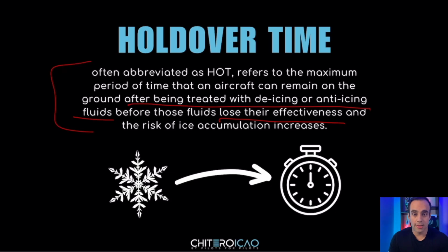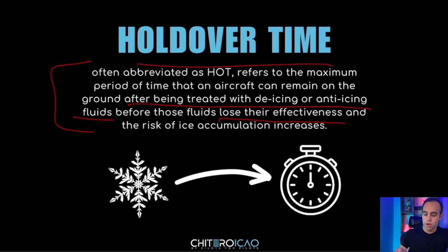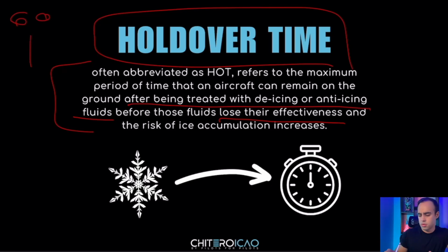It's very expensive, so after you do it, you need to get out of the ground, you know. So sometimes it's not possible. It happens a lot at the end of the year. So you're at JFK, you anti-ice your aircraft, everything's ready, but then you have 2 hours before takeoff because an aircraft had a problem. You lost that already. You have to redo the procedure because of the holdover time. If I'm not mistaken, it starts with 60 minutes and goes until 120 or 130 minutes, you know.